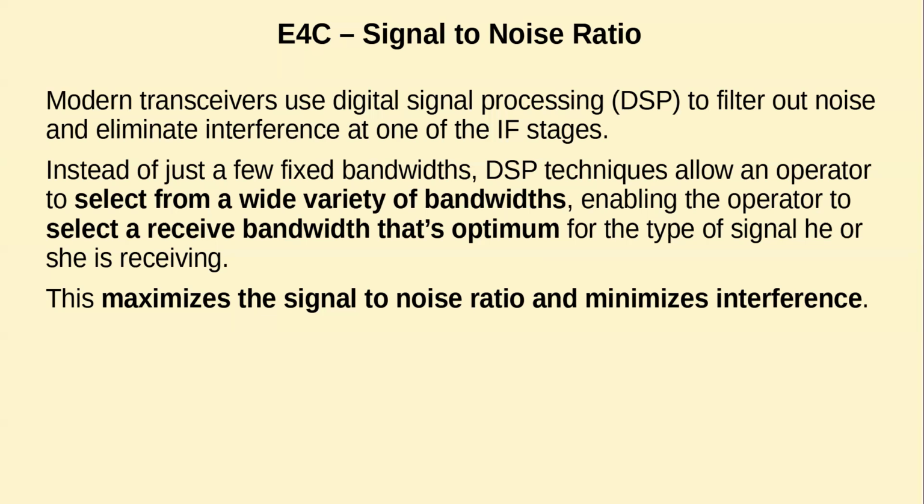The one exception to that is in the case of some of the digital modes like FT8, which is only 50 hertz wide, but there you do single sideband and have a 3 kilohertz wide filter because you're looking at the entire spectrum, basically, at 3 kilohertz wide and looking at multiple signals at the same time. Whereas when you're doing CW or phone, you're trying to concentrate on a single frequency.